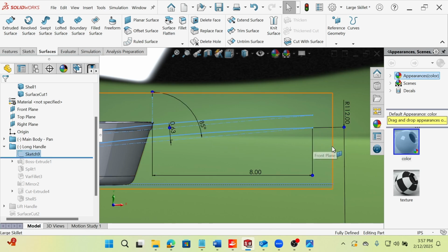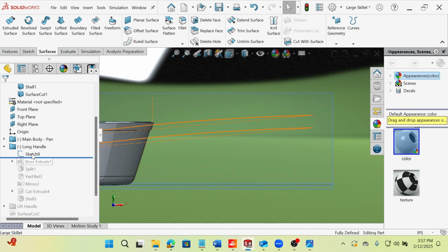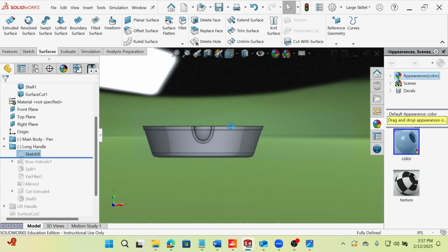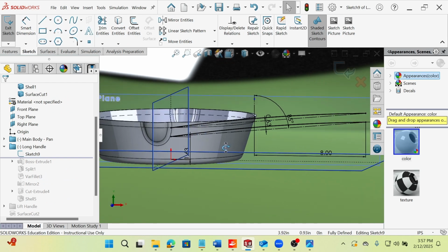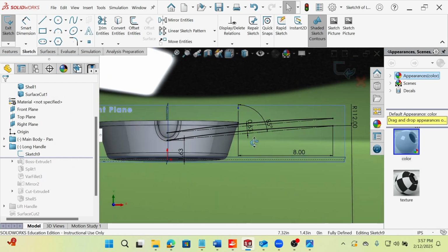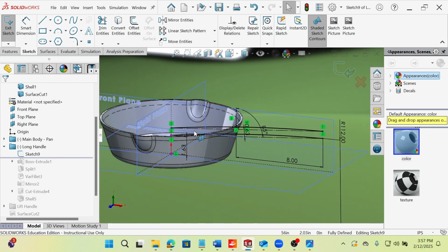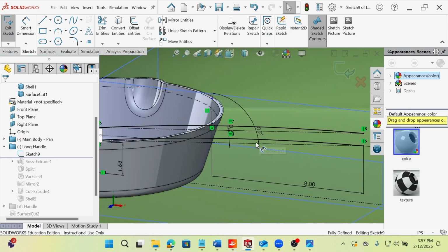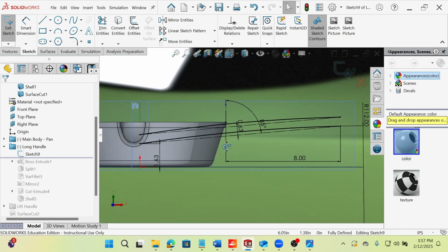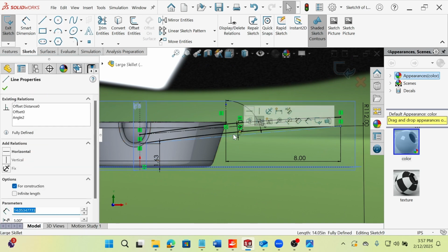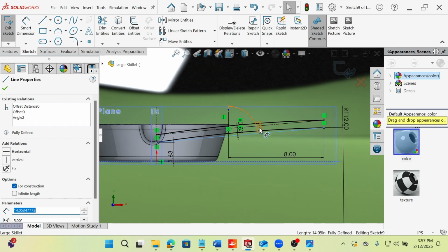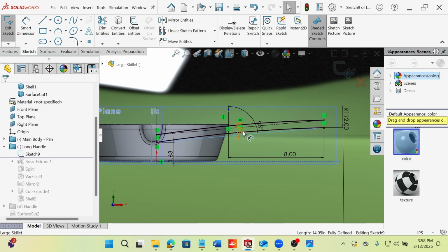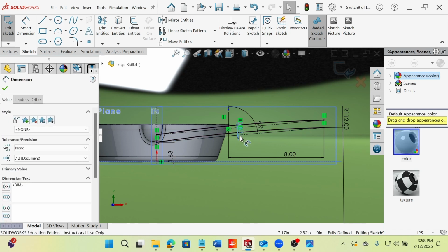So this is what I started with, just a quick sketch. Again, on the front plane. So I'm looking at the side of my pan. These are my 2 pour spouts, so the pan's going to be on the side here. And I just want it to have a nice arc. So first, I set up these just straight lines to use as a guide for the angle. And then I managed the distance between them to be 0.625 inches.